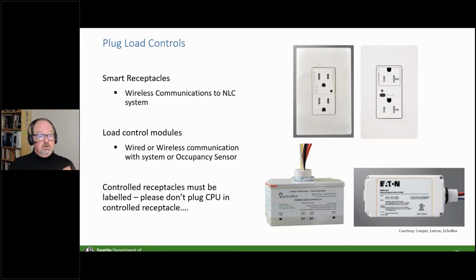So it will turn the lights on or turn the lights off. Another way to do that is with regular receptacles that are then controlled by a relay pack that looks an awful lot like one of these guys, typically 20 amp relays that will take signals, take commands from the system as required.